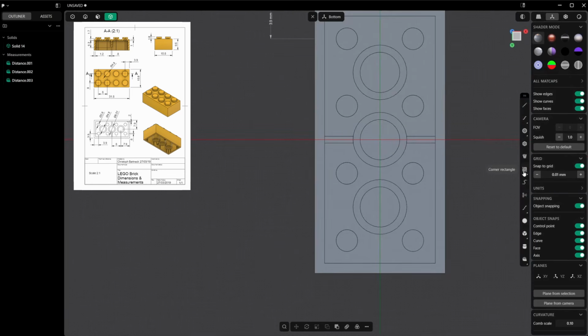I'm going to grab a corner rectangle. I know the size that they need to have, and they are aligned with my circles here. So with the corner rectangle selected, I'm going to start dragging from here. I'm going to drag to the other side so that I get a longer C, so that it spans the whole distance. You can see this way it doesn't. This way it does. I'm going to do the same thing pretty much that I did for the center one.